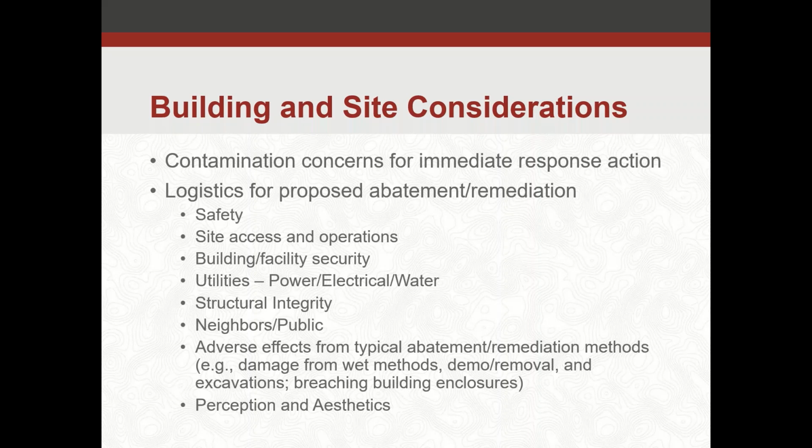Structural integrity: when you remove a material, it may not necessarily be good for the structural integrity of that building. So how do we plan for that? Is it something beyond what the abatement contractor can handle as well? Do we need to plan on some allied trades type scenario where someone else who can do that work can come into the work area, set up some controls, some systems, some temporary structures to allow that structure to remain intact as they're removing the